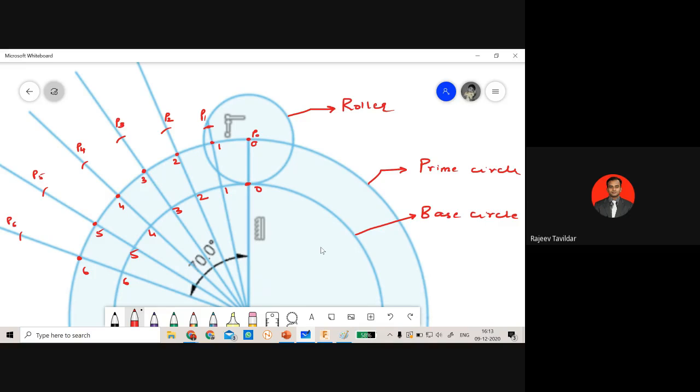Now, these are the center points of the roller follower. So I need to go on drawing the roller follower at every point. If you actually draw it, it becomes a little bit shabby. So what you can do is, keeping the center as P1, set the roller radius as 10 mm and draw one simple arc like this. Let me change the color here.